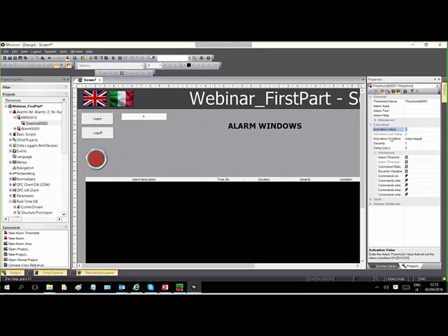There is also a good script interface for this object. So for alarm messages, this will call the information directly from the database. History of our alarms: you can filter, sort by one of the columns, you can print, and you can refresh the history of the alarms. So this is how you can review your alarms: the classical alarm window, or the banner, or the historical alarms through the log window.